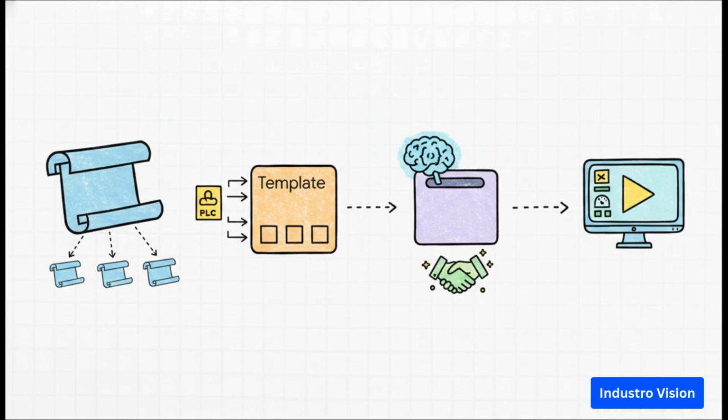Okay, let's lock this in. First, start using faceplates. Seriously, it will slash your development time. Second, use aliases to make those faceplates generic, so one template can work for hundreds of different motors or pumps. Third, when the built-in tools aren't enough, C# NetLogic is your best friend. Fourth, remember that magic handshake, the ExportMethod attribute. And finally, don't be afraid to experiment. You can test everything we just did with live data from a PLC using the emulator that comes with the free Studio license. There's zero risk.